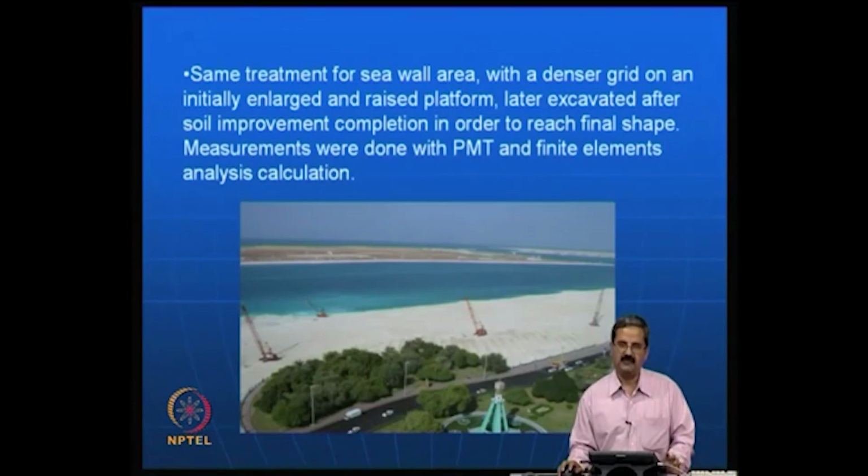It has been quite effective because the method itself is quite simple. It only involves the weight to be dropped, and everything is pre-designed, for example the height and the spacing. The only problem is to what extent you are correct, whether the ground is improved. That can only be ensured by proper in situ testing using SPT, cone penetration or pressure meter tests. Once it is done, it is ready for further construction.